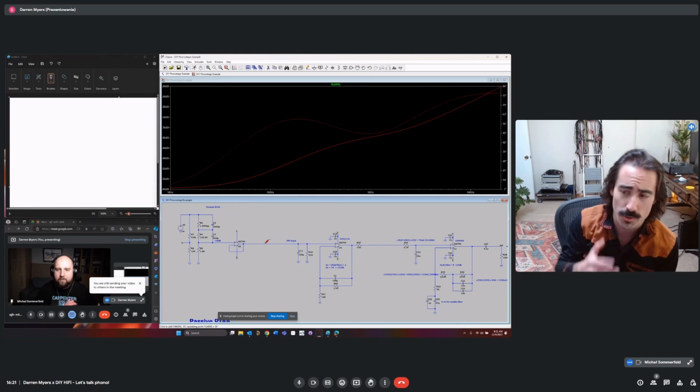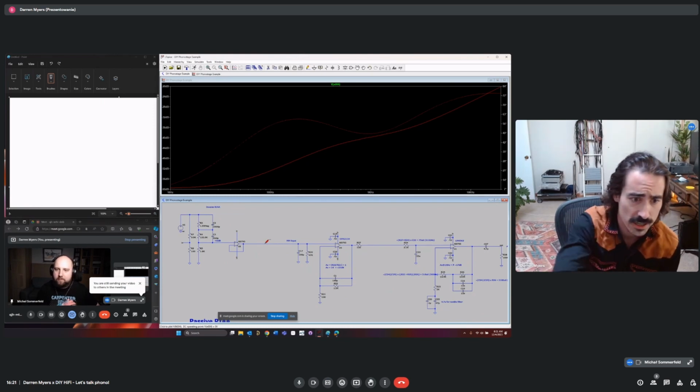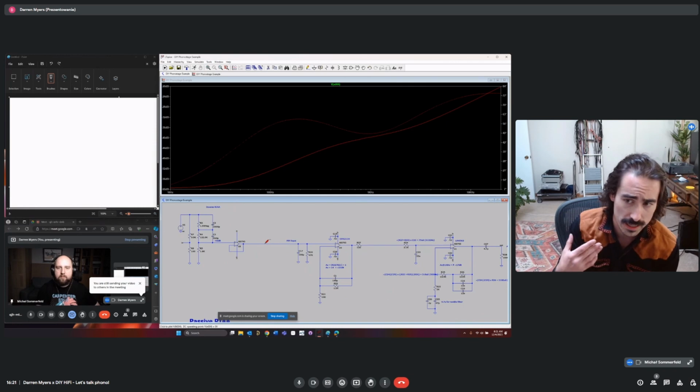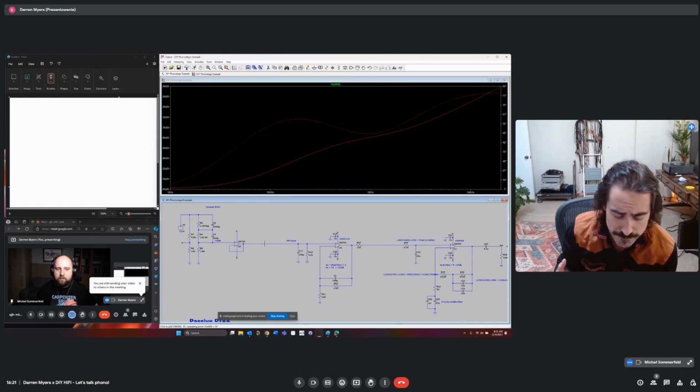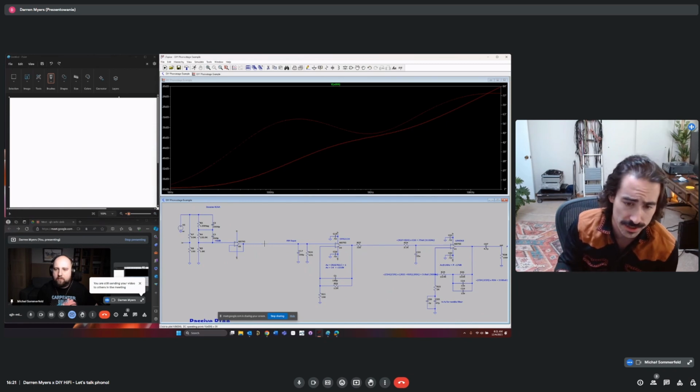So this is what's happening. What we have to do is apply the inverse transfer function. We have to apply gain to this entire waveform because it's very low amplitude as well. So it's coming off the cartridge here at, let's say, 1 kilohertz, at roughly 5 millivolts for an MM here.